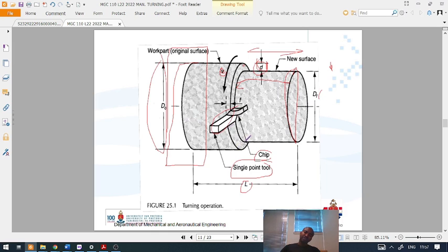Otherwise, if you stop somewhere in the middle because somewhere you will have your jaw holding it up, your L is not going to be the same. We will give you the true length of the block. We will give you how far is your component and ask you how much material you are going to remove if you need the depth of whatever. That is a volume calculation. It shouldn't be a problematic calculation.